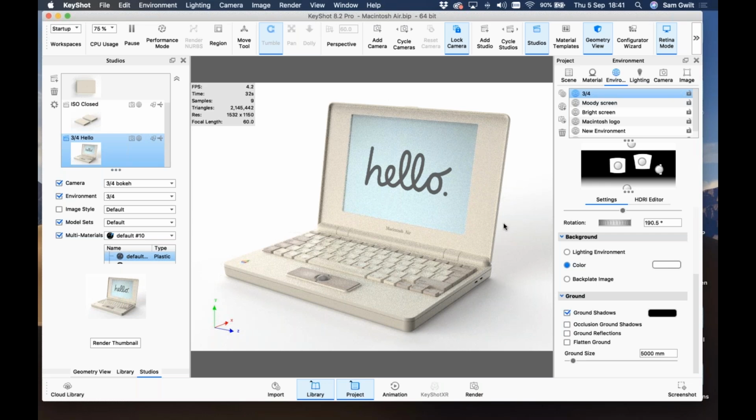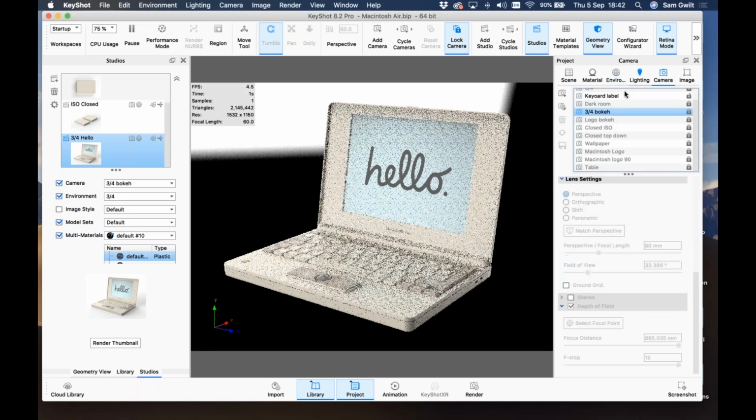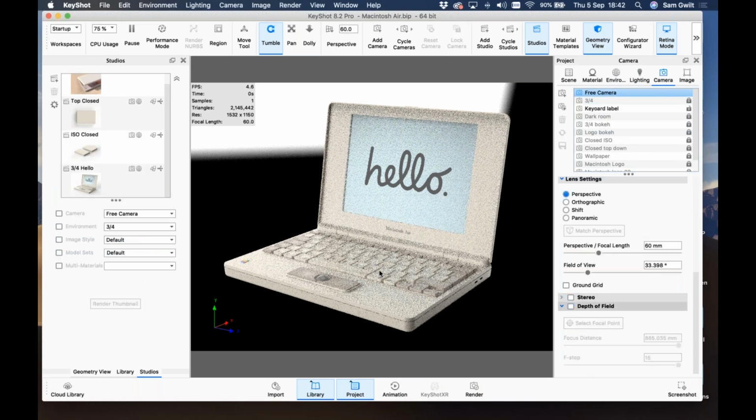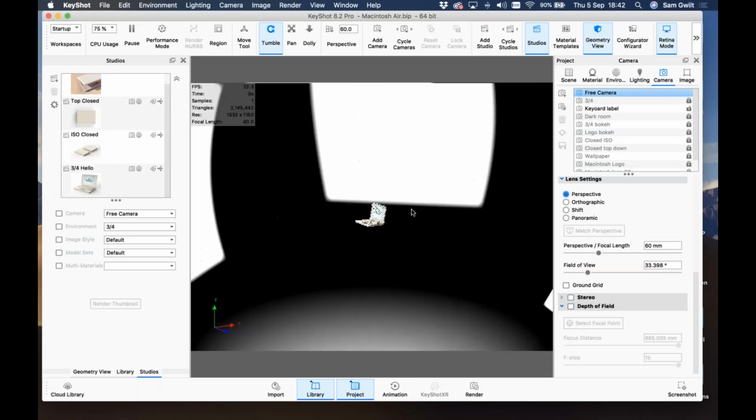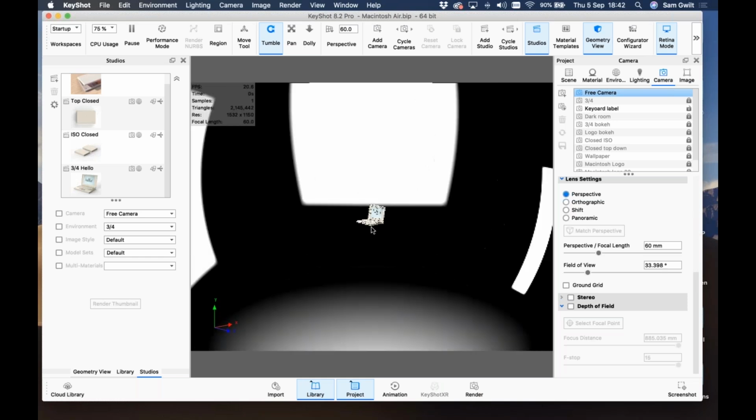But let's say you have a plane really close up to your model, let's say here, and you're pushing light this way. This area of the model is going to be extremely bright, whereas this one over here is going to be really dim, because the distance between here and here is bigger than the distance between here and the plane. So I just wanted to pick up on that and say that's why an HDR is really useful, because you can make sure that the render is lit from a nice far away zone,